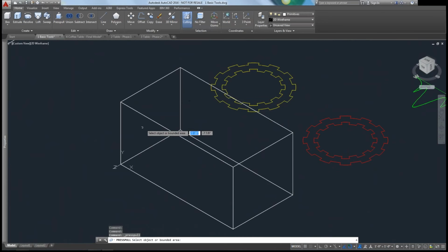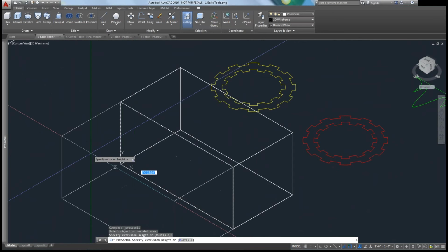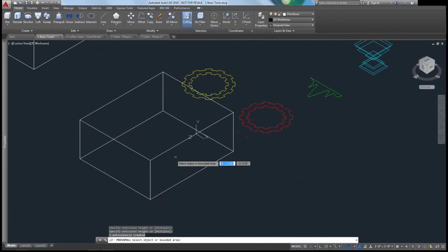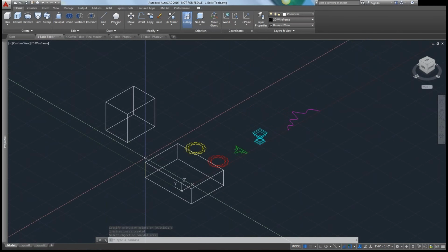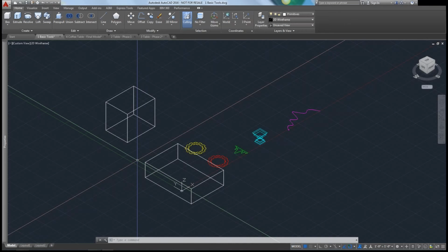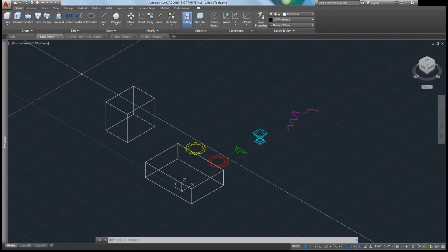You can just grab these faces and pull them out as you'd like. Press pull is more of an advanced extrude command where it allows it to be dynamic along all of the 6 sides of the object, or for a box anyways. I hope that answered your question. If not, please let us know and we can dive a little deeper at the end.